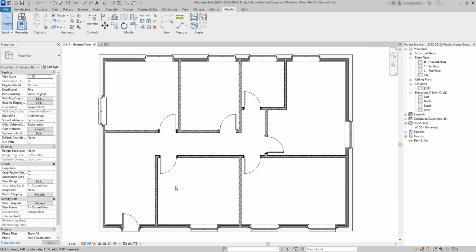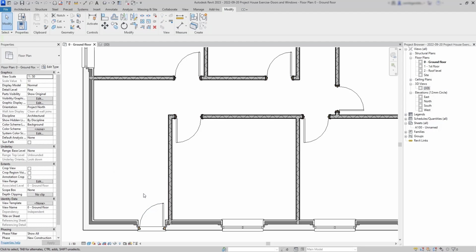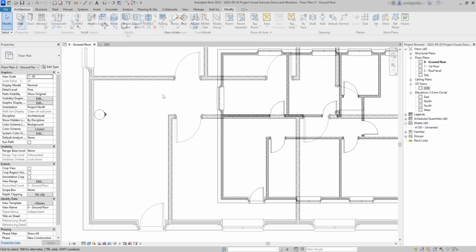Okay, first, in order to have enough room, let's move the exterior door to the right of the main hall. After clicking on it, I'm going to change this distance to just 100. Then I also flip the door to the other side. Okay, now let's insert a stair.